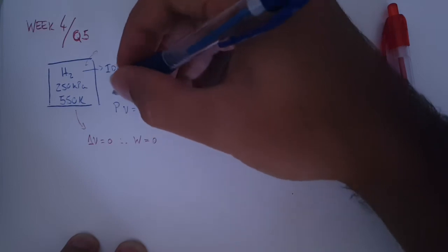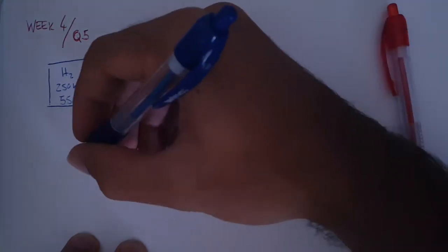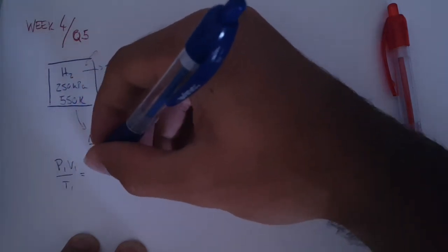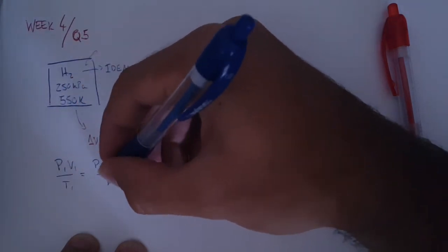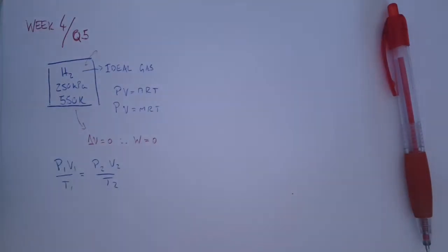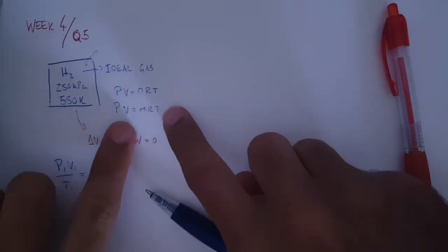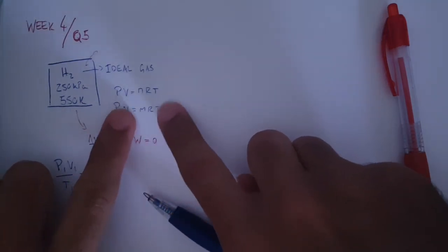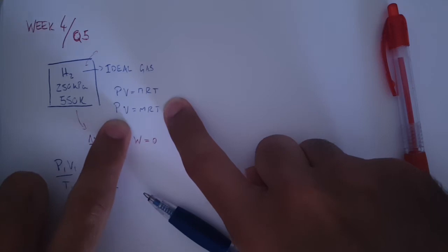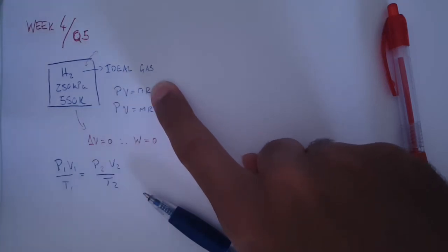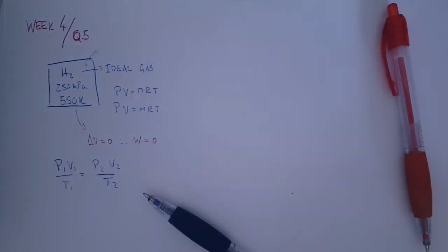know is that the relationship P1 V1 / T1 has to be valid as well, right? P1 V1 / T1 has to be equal to P2 V2 / T2. Why? Because if you look at this equation here, if you isolate one of the sides, what remains if you send the T that way, dividing, we're left with the mass and the ideal gas constant, or the number of moles and the ideal gas constant, right? So therefore, this makes our lives easier. Cool, so let's tackle this problem.